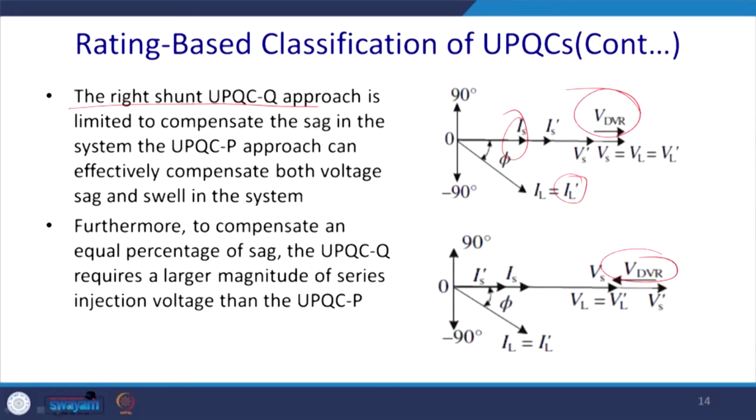The UPQC Q approach is limited to the compensation of sag in the system. The UPQC P can effectively compensate both voltage sag as well as voltage swell of the system.